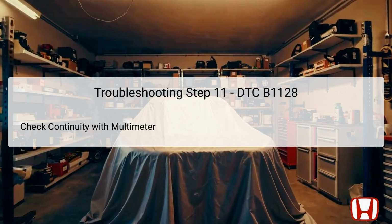In this crucial step, you will check for continuity between body ground and under-dash fuse relay box connector T34P, terminals number 27, unlock, and number 28, lock. Utilizing a multimeter for this task is necessary to ensure accurate readings. Continuity testing will reveal whether there are shorts to ground, affecting either the lock or unlock wiring.